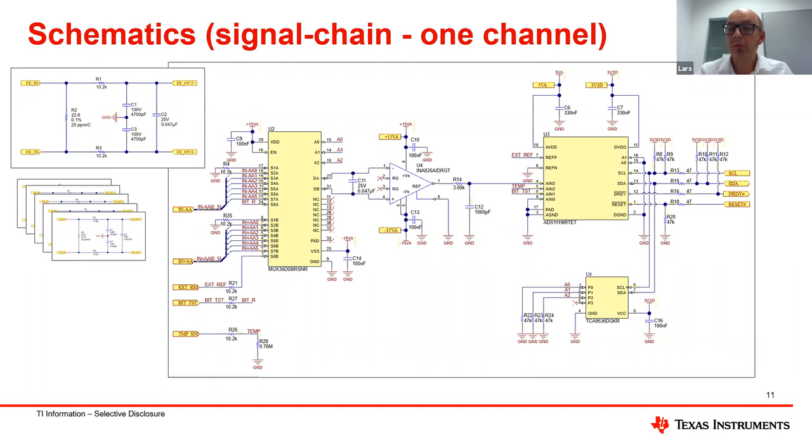for multiple reasons. First, I needed a multiplexer with 4 inputs. This was good. I needed an A to D converter with an internal reference, also important. And I also wanted a very simple device, not very complex in terms of registers. We will also say later that it has advantages to have maybe only 1 or 2 configuration registers instead of 20 or 30. So this converter was just right and talks with I2C to our processing unit.